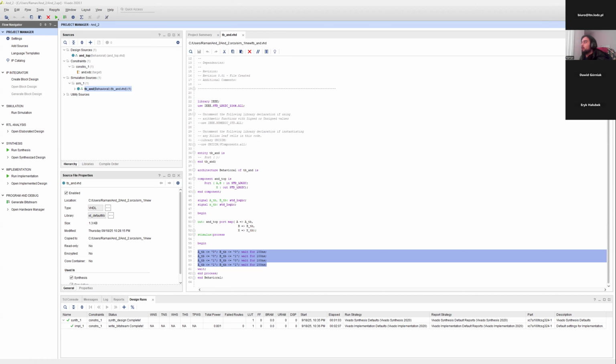So this is one of the ways you can verify that your logic is working. And this is just a simple way that you can do this, but of course there is the board that you can implement your code in. And now for that, what we're gonna have to do is create constraints. So it's either this, just create constraints from here, or what you can do is run the implemented design, wait for a bit, and it's running right here.